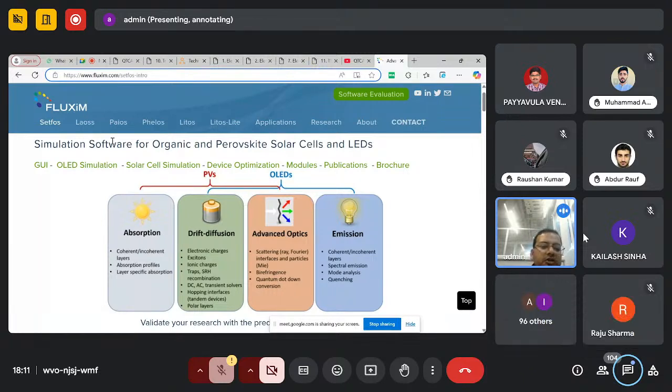So the smallest system configuration is for SETFOS, then more configuration for QTCAD, and even more configuration is required for Nanodcal and Rescu software. This is because SETFOS is a one-dimensional simulator based on drift diffusion, which will solve your equations fast. QTCAD requires a two-dimensional FEM-based simulator, and FEM-based takes a little higher time as compared to SETFOS.